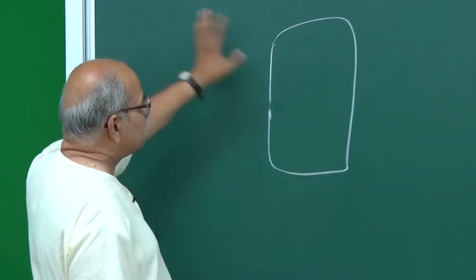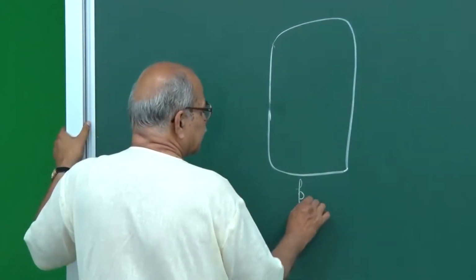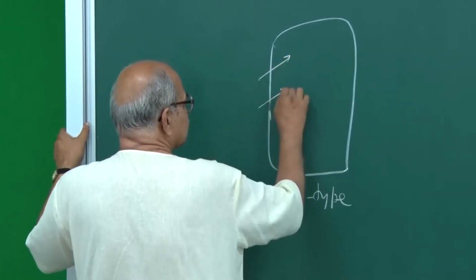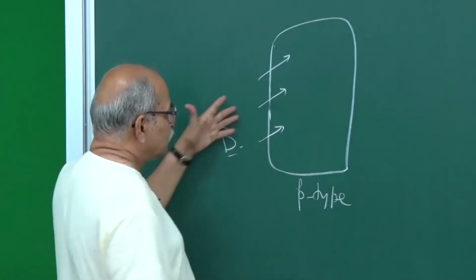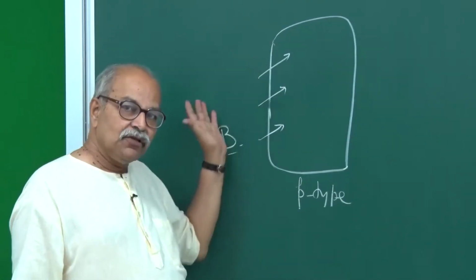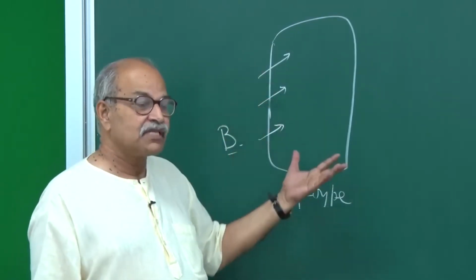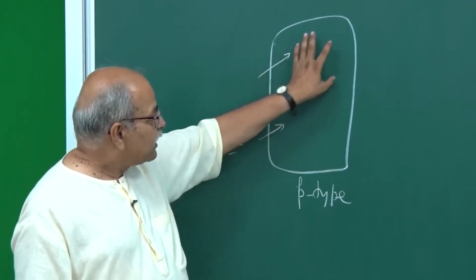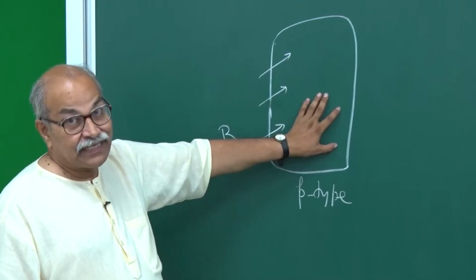So, that is the starting material, and with this starting material, the first thing is this entire wafer is made either p-type or n-type. So, let us say we make it p-type. To make it p-type, you have to diffuse a trivalent impurity like boron, so it goes there. Here also you have very controlled processes. There are several processes by which you diffuse these impurities, and at the end you retain that silicon crystal.